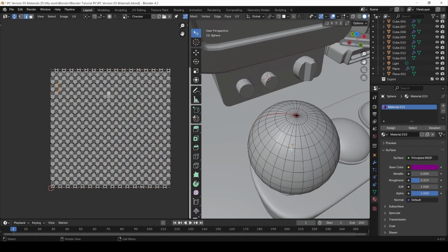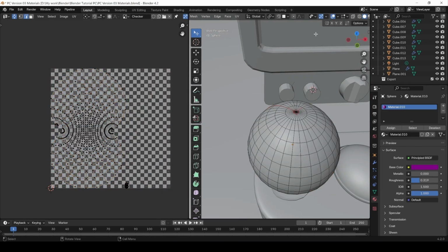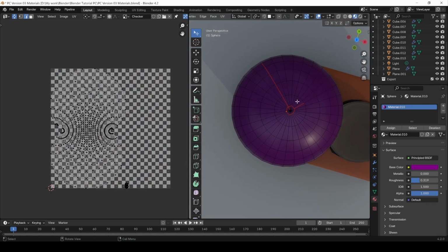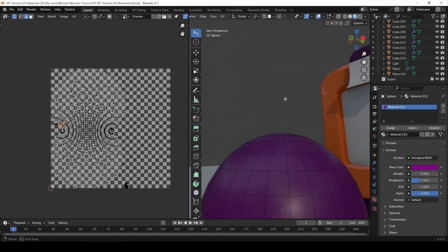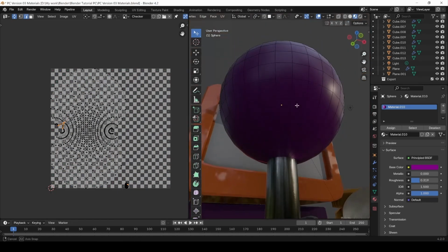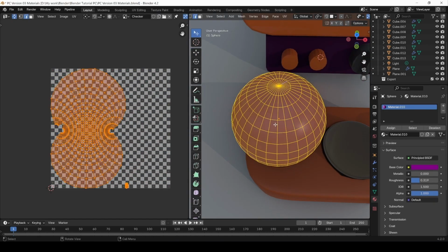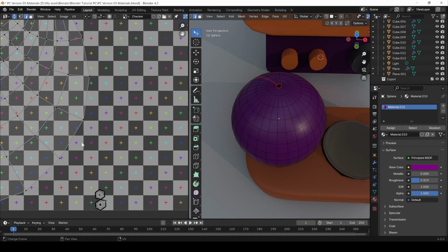Okay, now if I press A and select everything, U, or go to UV and choose unwrap. We have unwrapped it like that. Now if you go here, nothing really shows, so let's just take this off, clear. Do we have another one from the bottom too? It should not be, so no. So let's unwrap again, and those small ones right here.